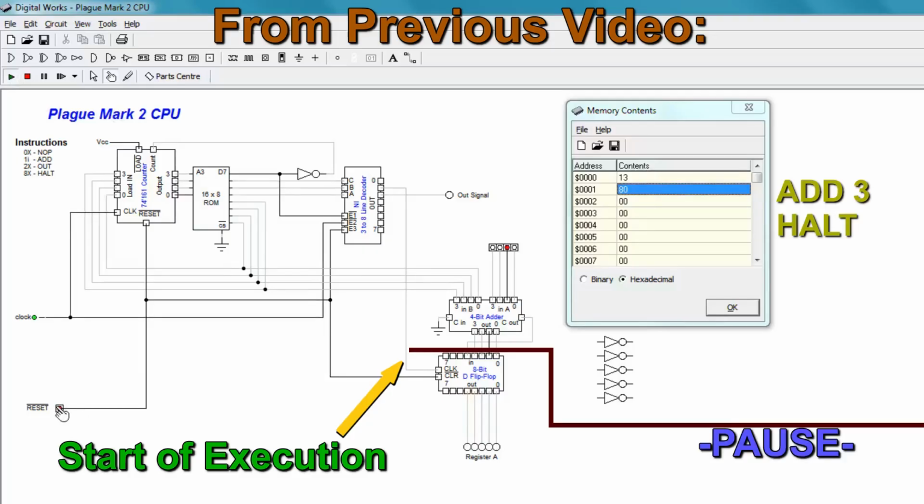The main clock then transitioned from low to high, which disabled the decoder and incremented the instruction pointer to the next instruction. Therefore, the register never stored the result of the addition. And now we are on to the next instruction, the out instruction, which ended the program. That's why the simulation showed 0 as the final result.